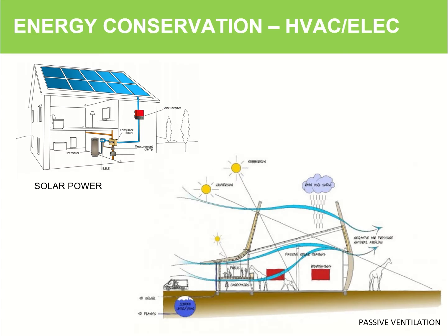One way is to, as we breezed over earlier, use thermal energy. Another is cooling through passive ventilation. The image at the bottom right hand of the screen shows how a habitat can do this. The building has a very sculptural roof that doesn't just act as a roof, but it's built at a specific angle to block the harshest sun, but also collect that thermal and solar energy to transfer into the building.